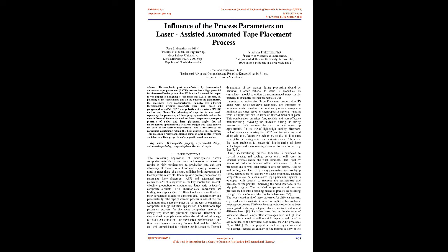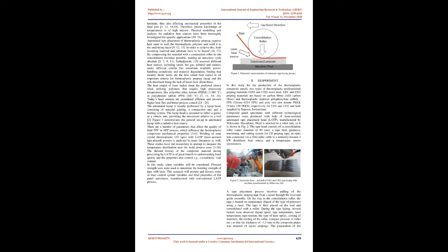Avoiding the autoclave during the curing process not only reduces the costs but also opens up opportunities for the use of lightweight tooling. However, lack of experience in using the LATP machine with laser, along with out-of-autoclave technology, results in laminates susceptible to having voids and resin-rich areas. Those are the major problems for successful implementation of these technologies, and many investigations are focused on solving them.